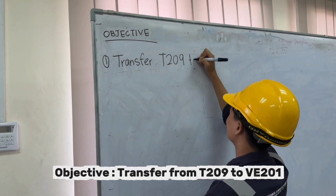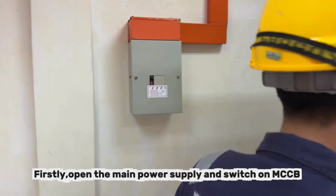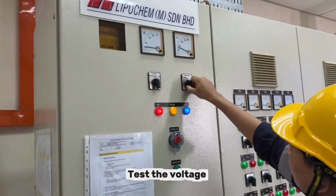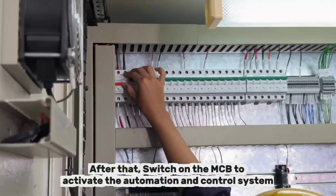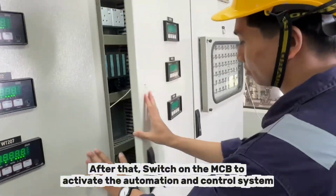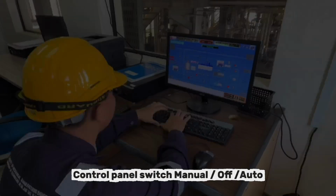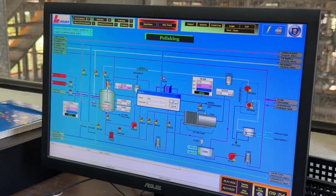Objective: transfer from T209 to V201. Firstly, open the main power supply and switch on MCCB. Test the voltage. After that, switch on the MCB2. Activate the automation and control system. Control panel switch: manual, off, or auto. Log in to SCADA to run the operation.